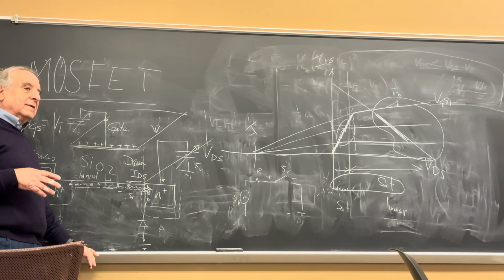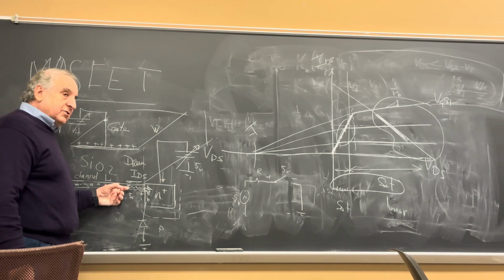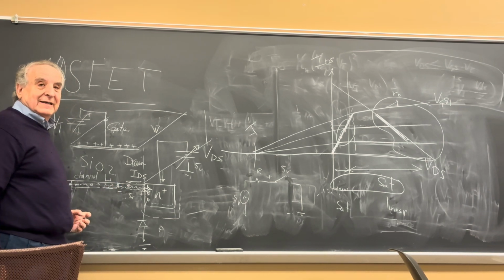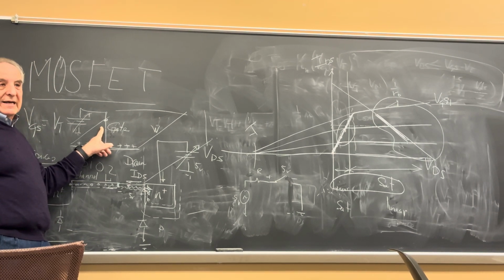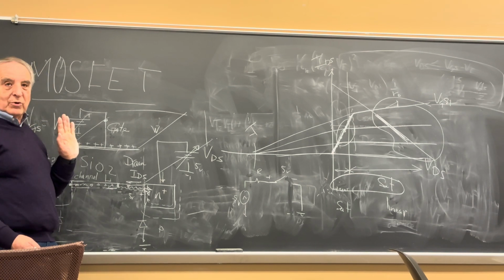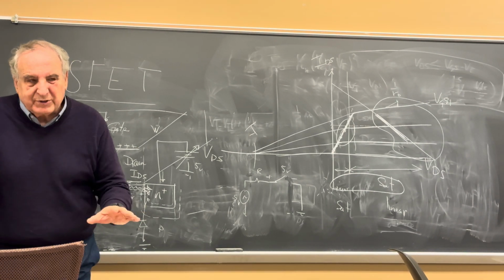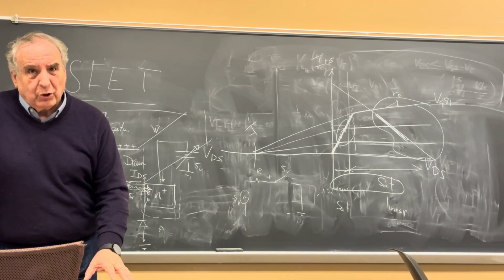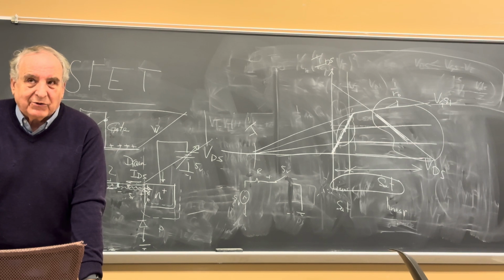There's another MOSFET called the depletion mode MOSFET, where the channel is there and you cut it off by applying a different potential. Instead of positive, you apply negative and push the electrons away. Depletion mode MOSFETs are normally used as resistors, active load resistors. Enhancement mode are for amplification because they're better devices.